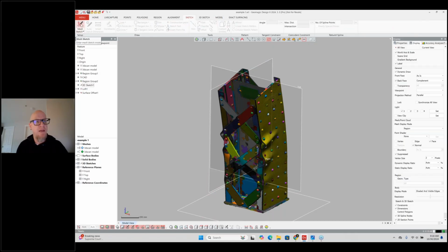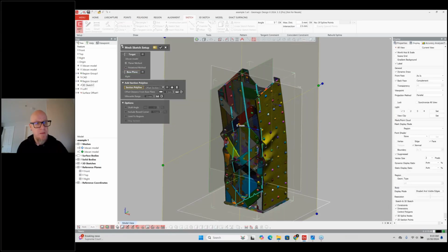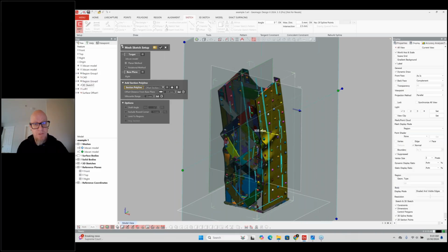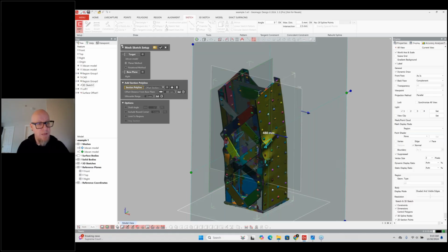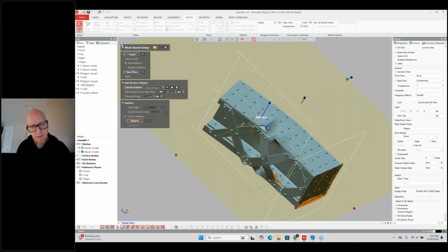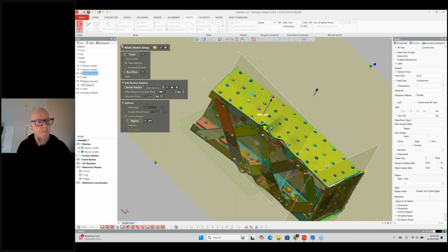I will extract information from the mesh on this plane here, and I will move closer to the plane. But what I want is to do it only on a specific region, so I will say limit to the region, and then I will select this region to avoid selecting other things, right?